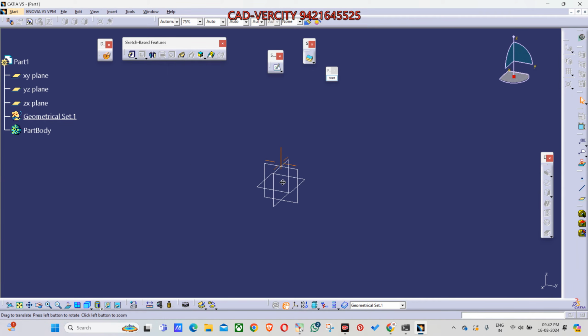Nearly 4 to 5 days you will take to control the mouse in CATIA. So click the middle button and move it like this. You will hold the 3D and you can move it. Middle mouse, right click one time. Move your mouse frontward, it will zoom in. Move your mouse outward, it will zoom out. Okay. So don't do anything for now.